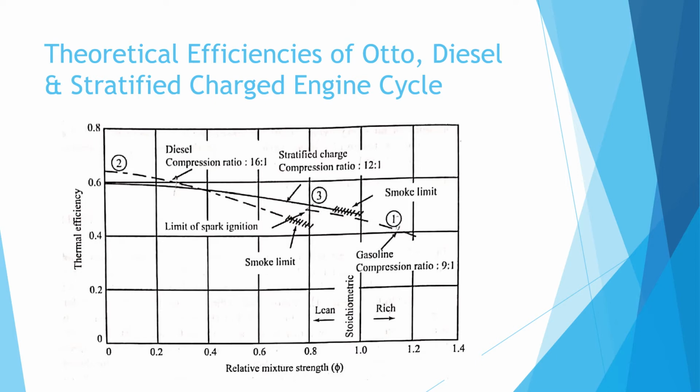Use of higher compression ratio brings with it a host of problems. It involves greater maintenance, higher mechanical losses and higher weight to power ratio. The poor air utilization results in poor fuel economy and smoky operation at higher loads.